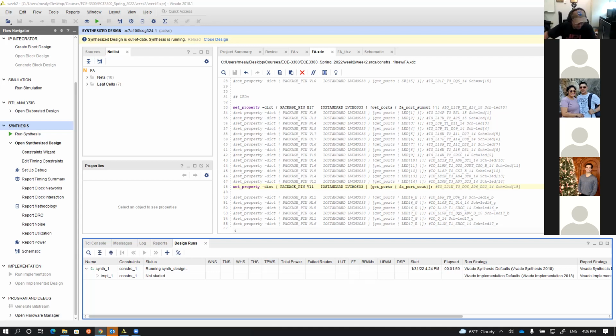Anyway, I think it's better to stop the sharing and leave it running until it's done. Then I will show you what's happening, okay? Because you're not going to miss anything. You run synthesis, after that run implementation, then programming and debug, you run generate bitstream. See, there is gray because it's not ready, right? So when it comes to this point, I will return it back to the tool, okay?